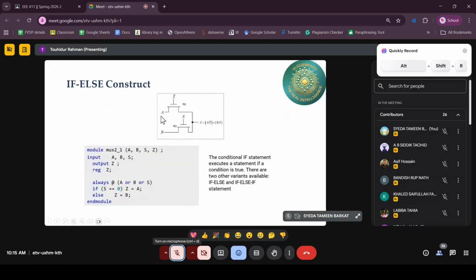For pass transistor, input is provided at the source and output is taken at the drain. So this is the fundamental difference, and as a result, we can cut off or disconnect the input and output of the pass transistor. I'm not sure whether you learned it in 283, but I'm sure Dr. Tisha will provide you a lot more details in terms of circuit operation and so on. However, this is the basic concept for pass transistor and CMOS transistor.